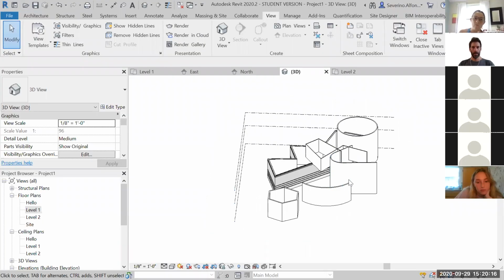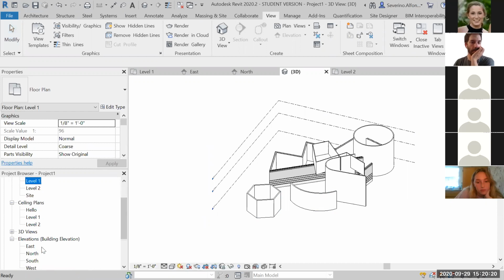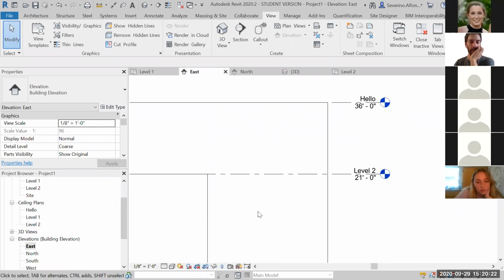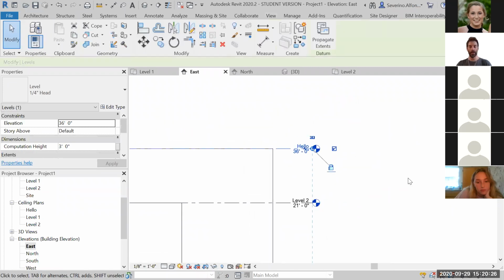So that's a good question. One thing that happens often, as I mentioned, is that if you, for example, in the elevation, see the levels 1, 2, 3, you might select a level and copy. What is the shortcut in Revit? Shortcuts in Revit are 2 letters. You press 2 letters and then you wait. You don't have to press enter like AutoCAD.